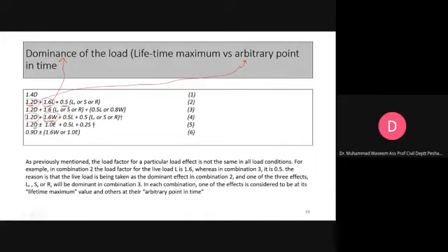They were not arbitrary, like, okay, let's make 1.2, let's make 1.5. No, they have used probability theories like reliability theory to derive these load coefficients or load factors. And this statistical analysis is always performed on real data. It was not performed on arbitrary data. So there was some original experimental data, and they have used reliability theory to derive these load coefficients, and that's why they have put that into the code.